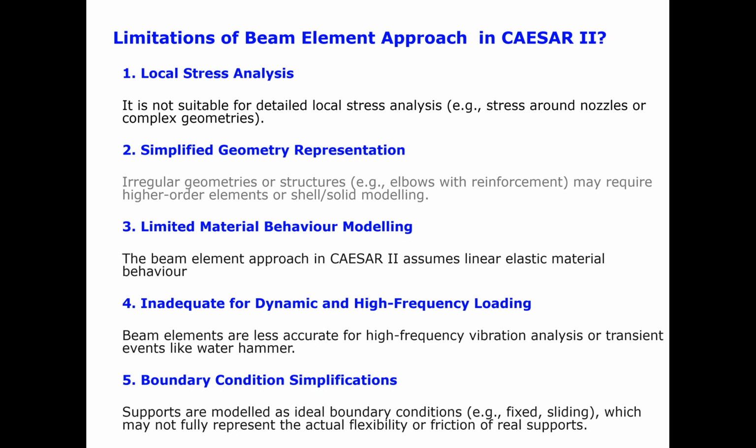Secondly, weld and flange stresses. The stress concentration at the welds or flanges is not directly captured in Caesar software. For such cases, 3D finite element analysis (FEA) software like ANSYS or Abaqus is used.